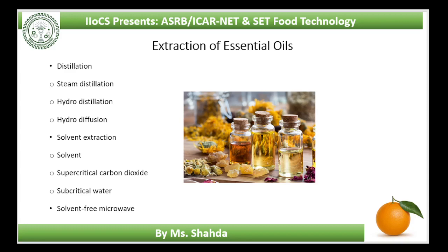Volatile compounds such as monoterpenes can be collected from the supercritical fluid extraction effluent by greater than 90%. Supercritical fluid extraction was able to recover some organic compounds that were not extracted by hydrodistillation. Supercritical fluid extraction is more economically viable than steam distillation. This is mainly caused by the lower yield and the higher energy consumption of the latter.